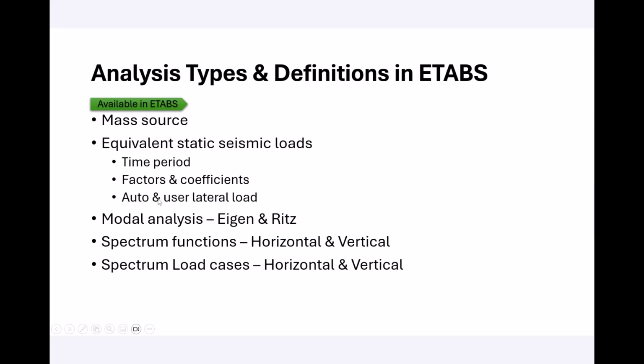Importance factor, Z value, and R value. So the lateral loads can be applied as the auto lateral load, which we are discussing so far, and it also allows the user to assign it as a user load. So if you have calculated the loads externally following a different guideline and you want to input that, then you can use the user lateral load.